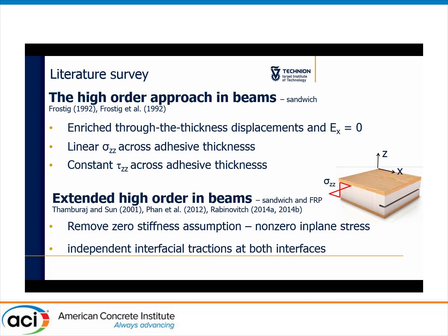An important consequence of this assumption is that the transverse normal stresses, sigma zz, which are generally neglected, are here not neglected and vary linearly across the thickness of the soft layer, which is necessary in order to capture the three-dimensional stress state and traction state at the adhesive and neighboring interfaces.